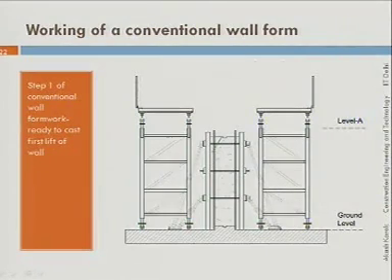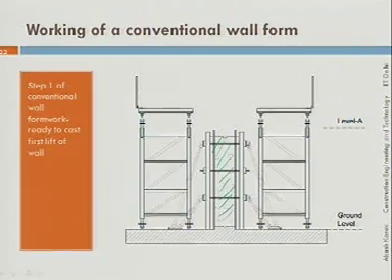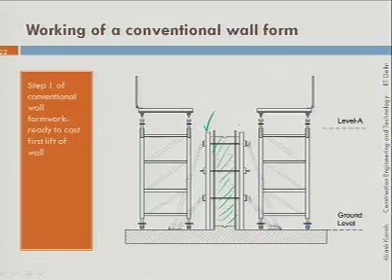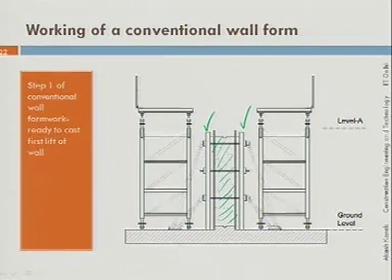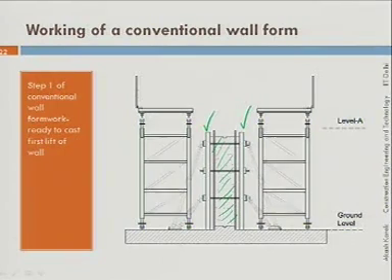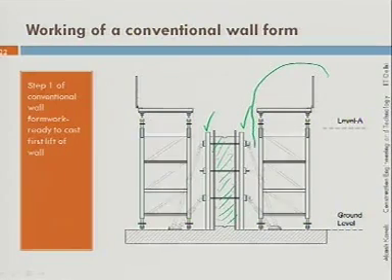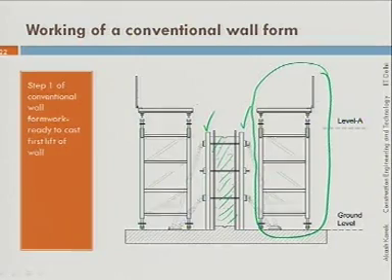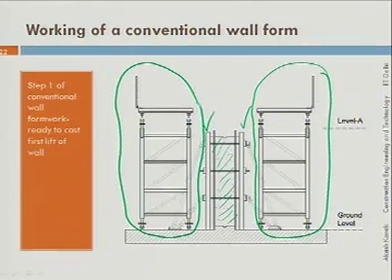Suppose you have to cast this wall. Okay. You have to cast this wall, right? So you will put shutter on this side, you will put shutter on this side, both sides, double sided shutter. So you have panel, you have soldier, you have walers, you have alignment props, you have tie rods. All the components are clear. Now in addition to this, you also need to erect this, both sides or maybe on one side. What for?